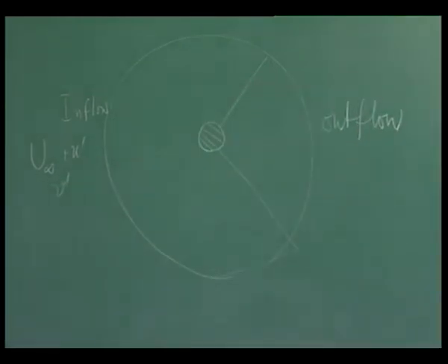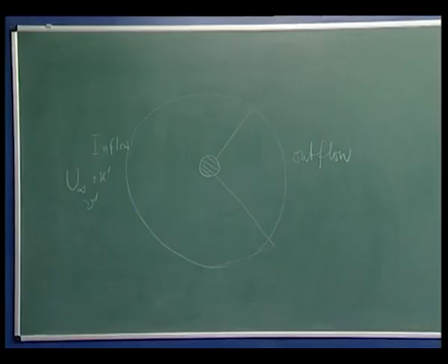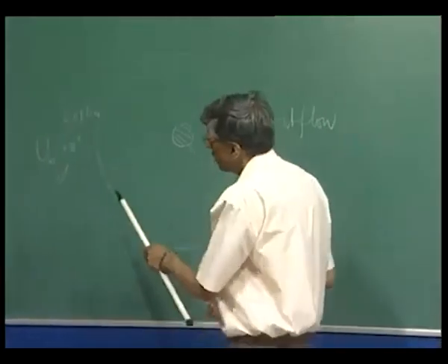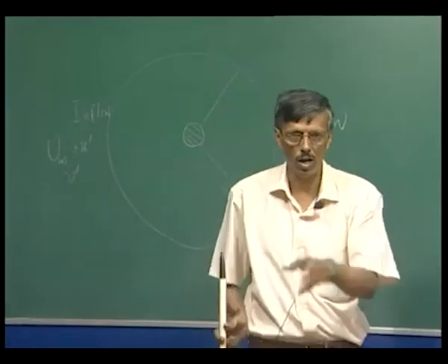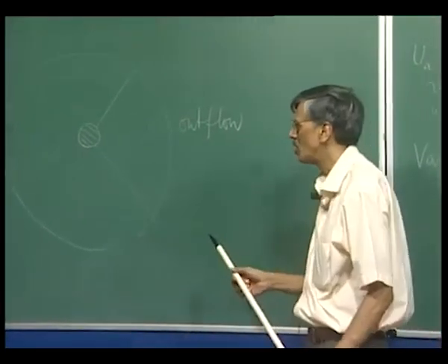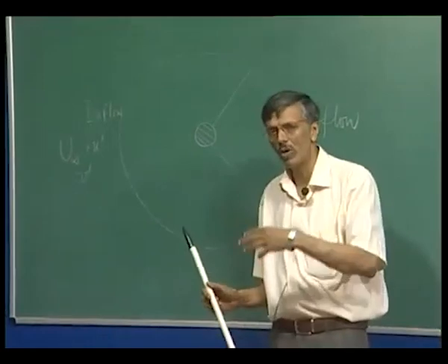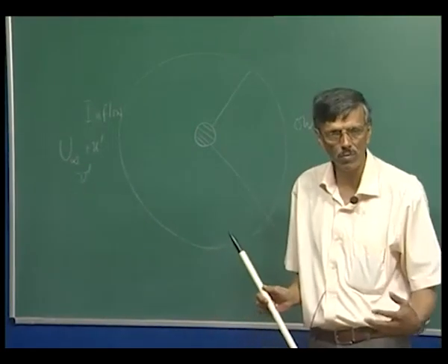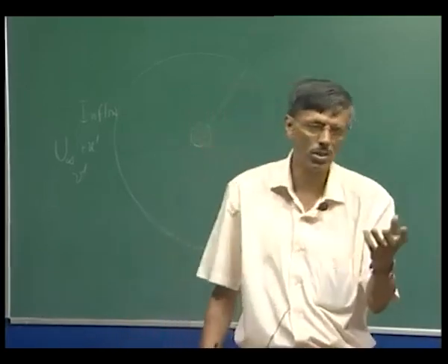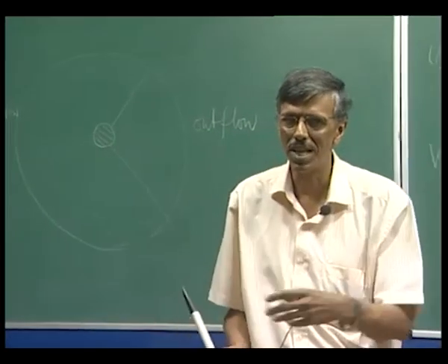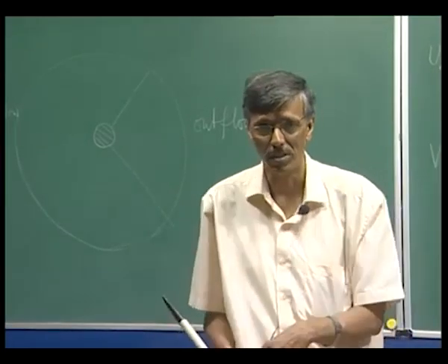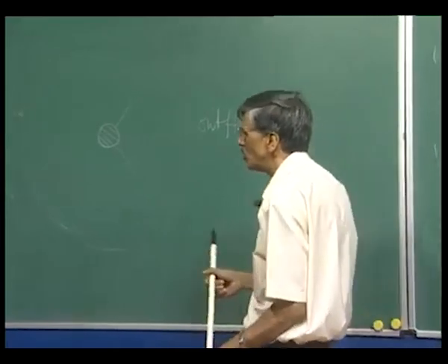Well, if you have done a pretty good tunnel design and the contraction is not too rapid, then it is quite okay to consider that u prime and v prime have the same statistics, a kind of isotropy you can talk about. But if you want to also include some additional information you may have, for example, in a channel flow, v prime is going to be less than u prime, then you can put it in there, and you can also get this nice wall normal structure. There are experiments available, so we can do that.